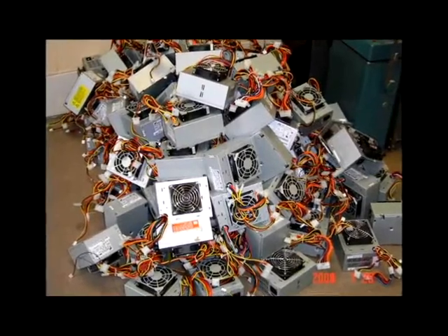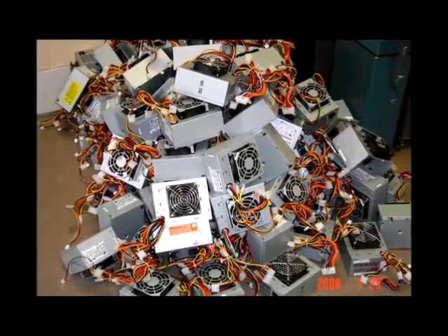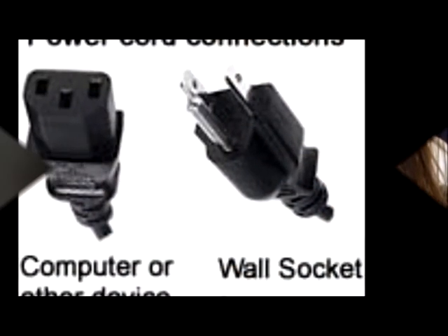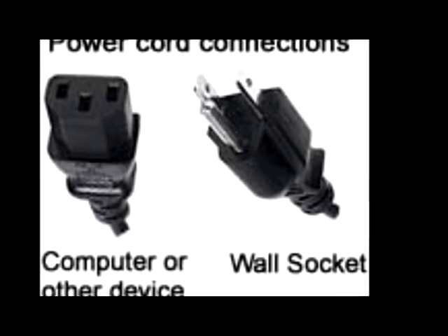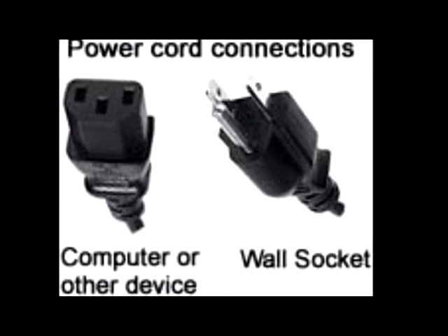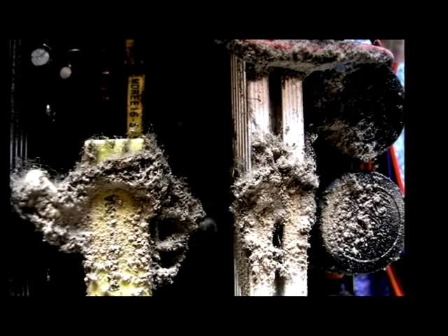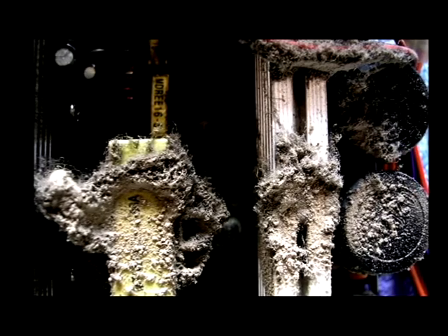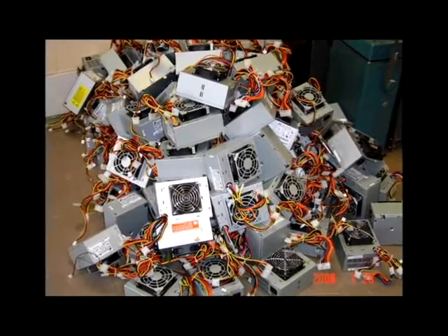Turn off the computer and disconnect all devices. Reinstall each device one by one, turning on the computer after each device. Should your system not come on after installing a particular component, replace it. If your system doesn't come on after reinstalling every device, you may have a motherboard or CPU problem.